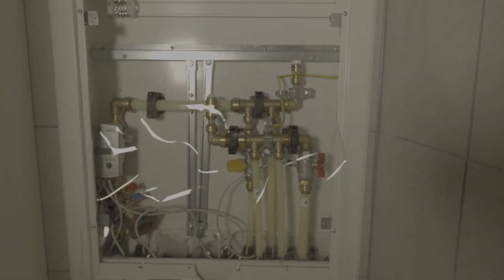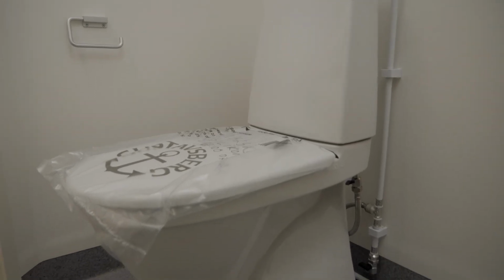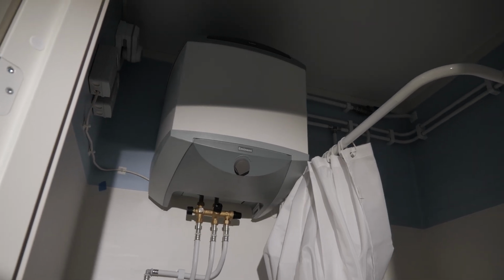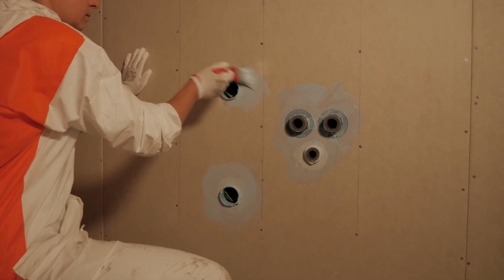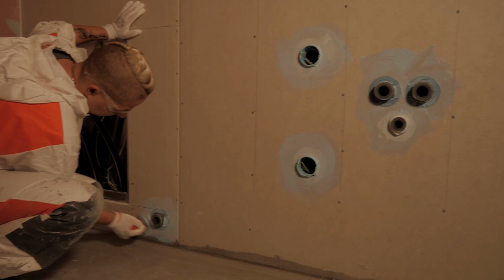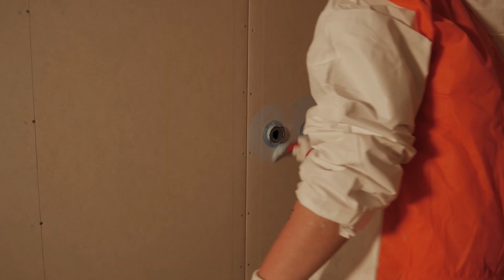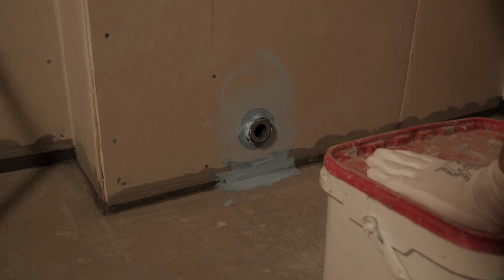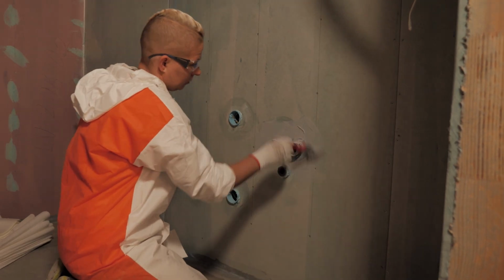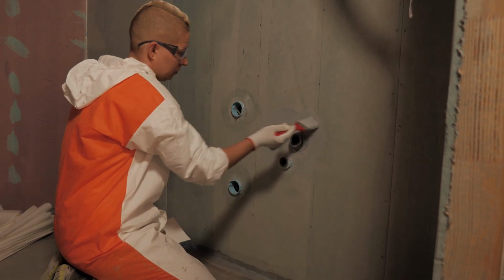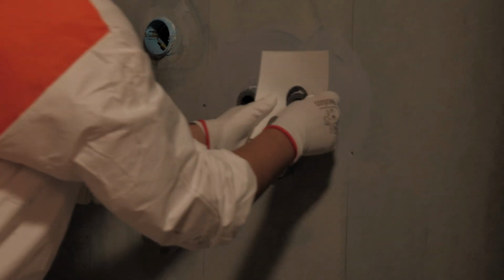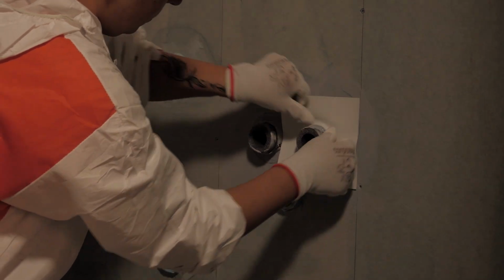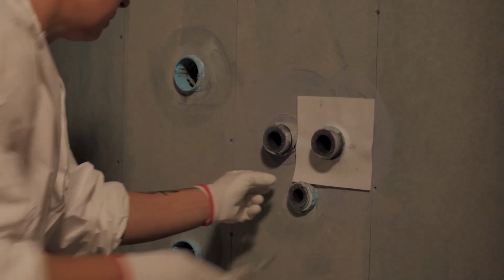In the bathrooms, the domestic water pipes are usually installed inside the wall element, but sometimes run along the wall's surface. The ends of the in-wall pipes are brought out at designated locations planned for water fixtures, such as a washing machine, sink faucet, or shower mixer. It is extremely important to seal the areas around the pipe penetrations because the moisture in humid and warm rooms moves easily through the gaps inside the wall construction and may condense there.